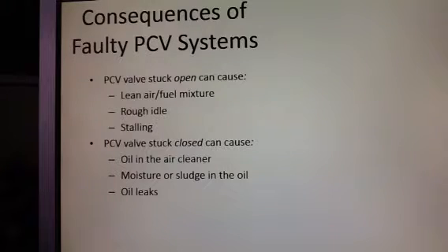Consequences of maybe problems with PCV systems. A PCV valve that is stuck open may cause a lean air-fuel mixture. So if you see that we're having problems with fuel trims, in that case we may be having something as easy as a stuck open PCV valve. We may have rough idle problems, and that can obviously be caused by a stuck open PCV valve. We could have stalling problems with this.